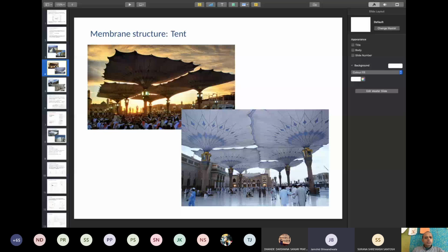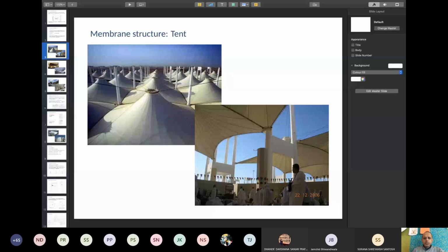Not only the support system, Somil, this in fact is very useful for diverting all your water through this post. So all the water that you're catching, you're directing it through a center space. But even otherwise, in the tent structures also, there are water barriers that you keep at the edges, and that will direct water. Like for example, in this structure, at these joints and even at the edge, this edge will not allow the water to drip like this.